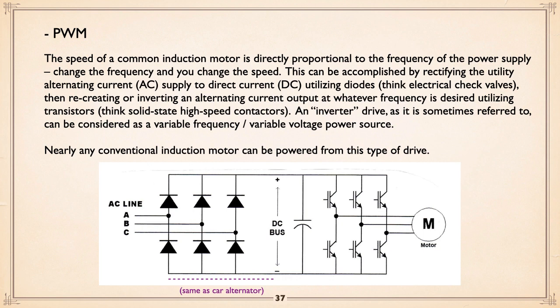And isn't that a miracle? But we don't have to deal with that. You've got a car with an alternator. That's how it works. Kid you not, that's how a car alternator works. The AC frequency varies as you rev the engine, but the alternator has diodes in it, which flip it all to DC, and there you are.